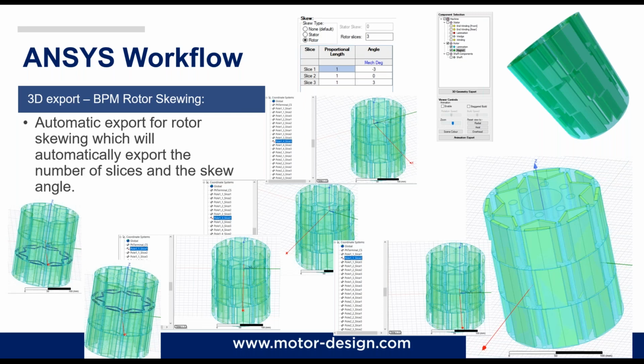Then we will have the insulation boundary condition between each slice. This condition is used to model very thin sheets of perfectly insulated material between touching conductors. It is an important feature because the insulation prevents the current from crossing the boundary. So in this scope it is used to control the flow of induced eddy current. So the 3D export can also be a good tool to investigate the magnet losses.